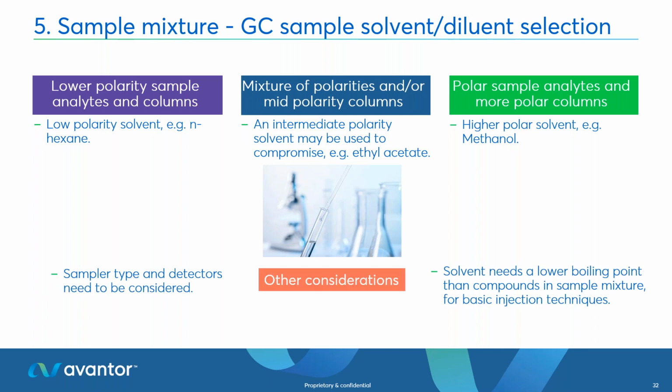And just the other considerations of the sampler type that you're using, detectors, you just need to double check that everything's compatible. And then if you're doing different injection techniques, check the solvent has a suitable boiling point. It tends to need to be lower than the sample mixture for most basic injection techniques.